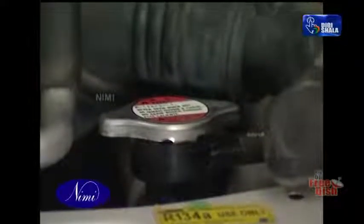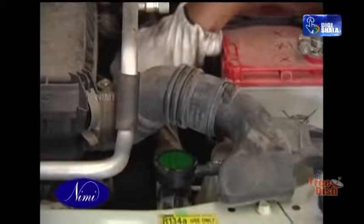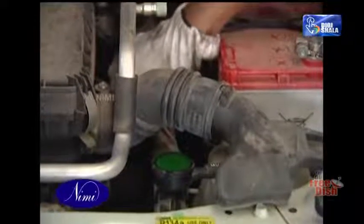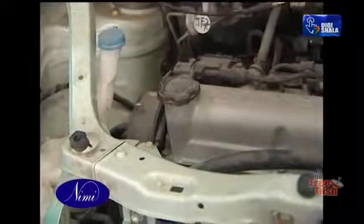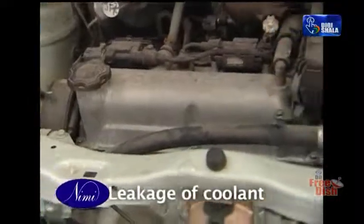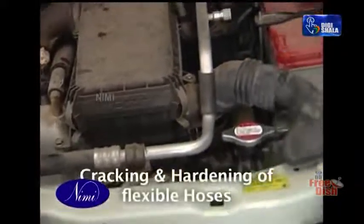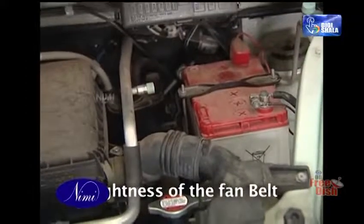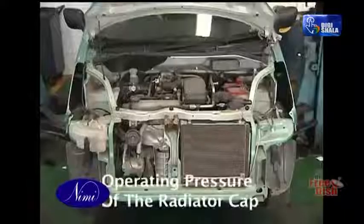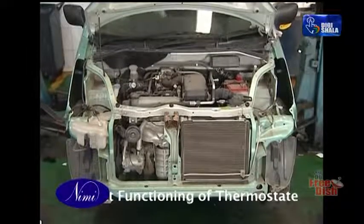Cooling system maintenance. The normal unsealed coolant system should have the coolant level checked and topped up with pure water if possible at weekly intervals. Regular inspection should be made for: 1. Leakage of coolant, especially after filling with antifreeze. 2. Cracking or hardening of the flexible hoses. 3. Tightness of the fan belt. 4. Operating pressure of the radiator cap. 5. Correct functioning of the thermostat.